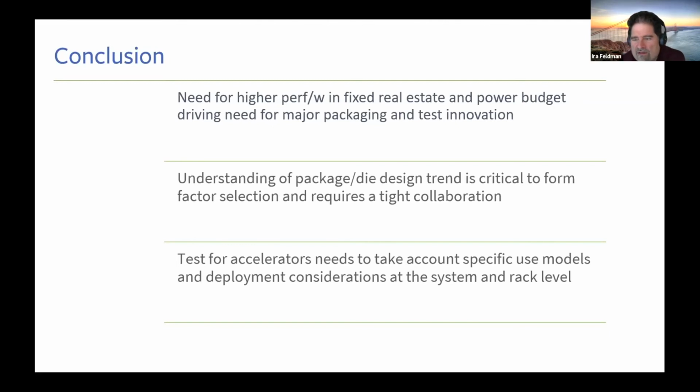Okay, got it. There was a question related to the chart you were showing, that as the package size increased, the power decreased, which intuitively doesn't feel right, because normally the bigger the die size, the more power consumption, assuming the same process node. So the y-axis was not power, the y-axis was temperature for the ASIC and what we had to do in terms of thermal capabilities to fit it into that envelope. Got it. Was that the junction or the case temperature, if you recall? Junction. Okay, got it.